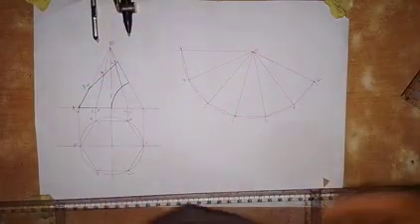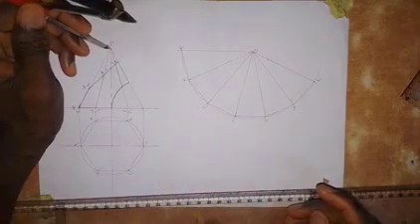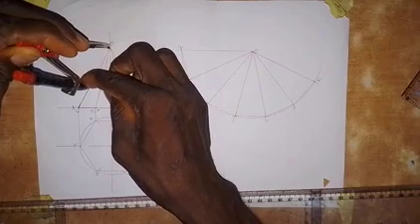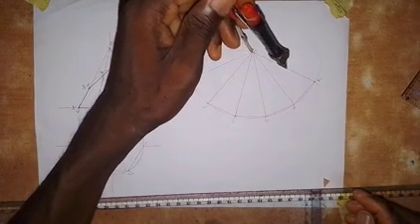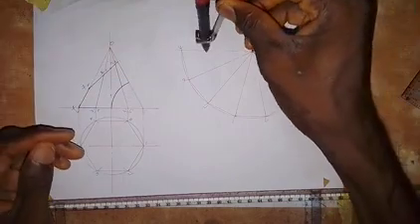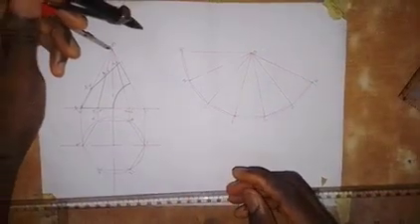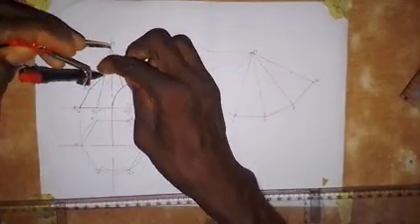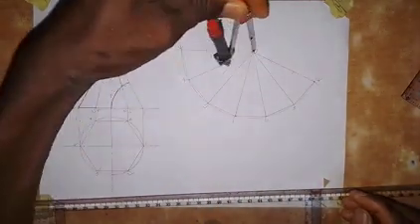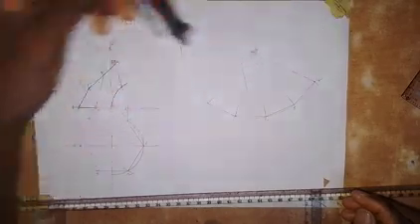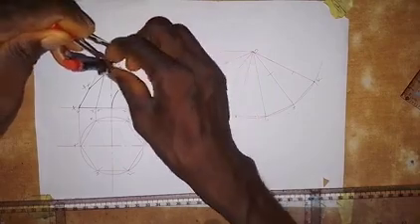If we are opening, let's work out this part that is cut off up here. Put the pinpoint of the compass here at point O, extend to this point 4. Then make an arc here on 4. Then we have 3 and 5, so put the pinpoint here at O, extend to this point 3 and 5, and make an arc on 3 and an arc on 5. Next we have 2 and 6, which is this point.